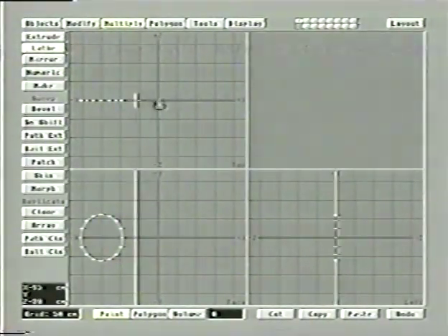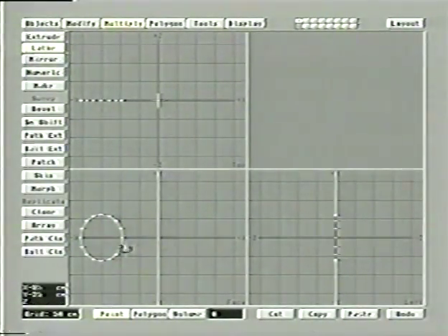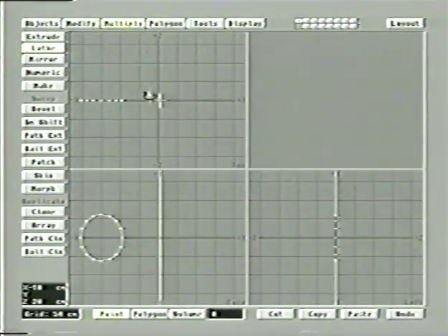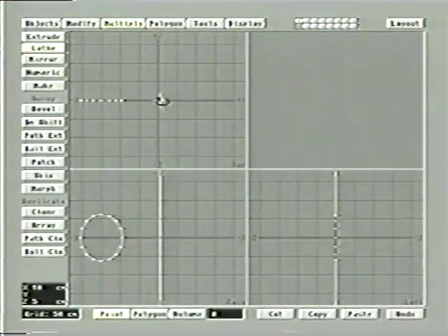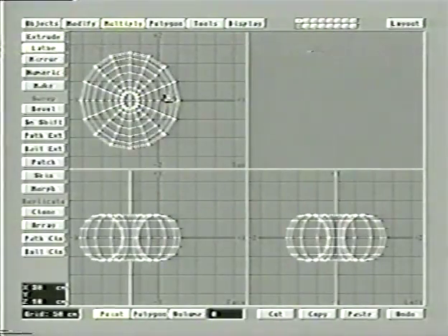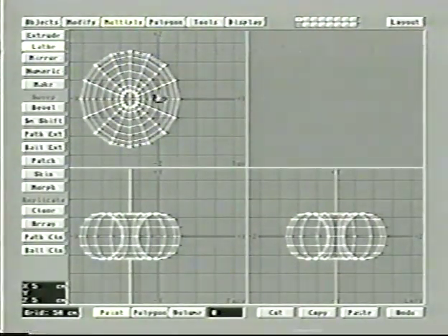And you see I'm dragging it in the top view, but actually where I'm watching is down here in the face view. Now, this is the pole around which it's going to sweep the object. So the closer the pole is to the flat object, the less it's going to sweep it. Let me just show you that, and I'll leave the lathe function in its default setting here. I'll move the bar in closer, just hit return, which is the equivalent of hitting make, don't forget. And notice it sweeps it around, creating basically a donut shape there.